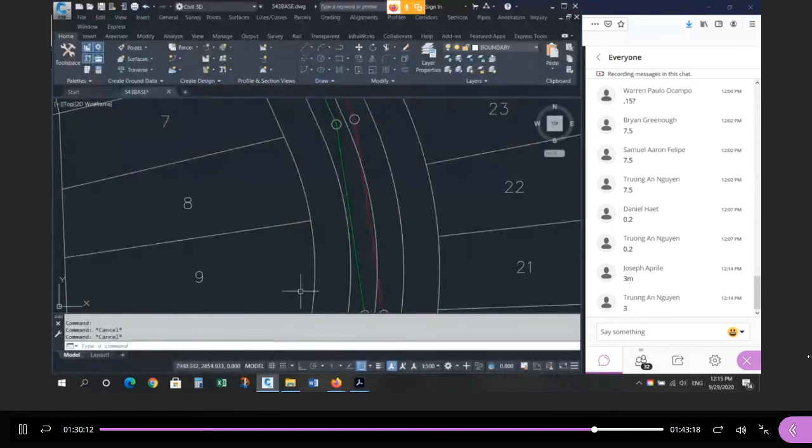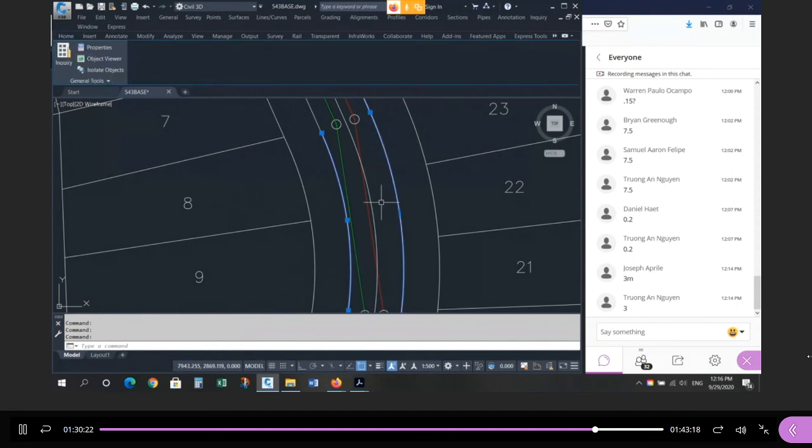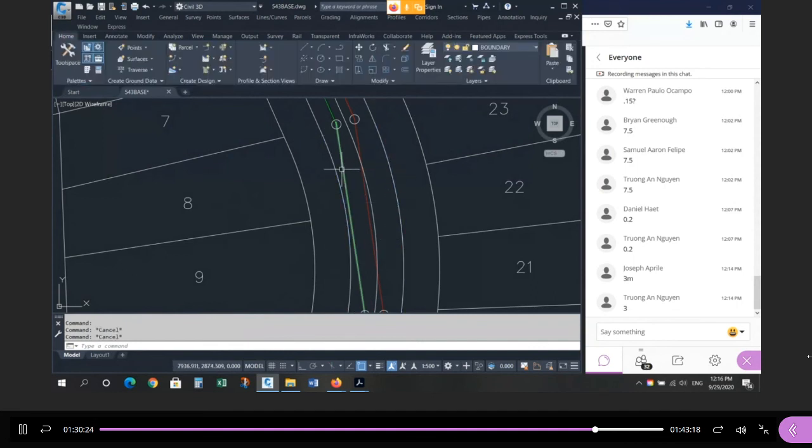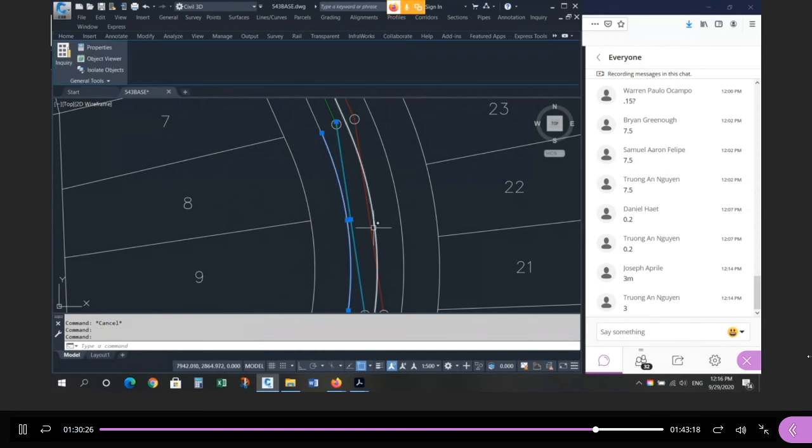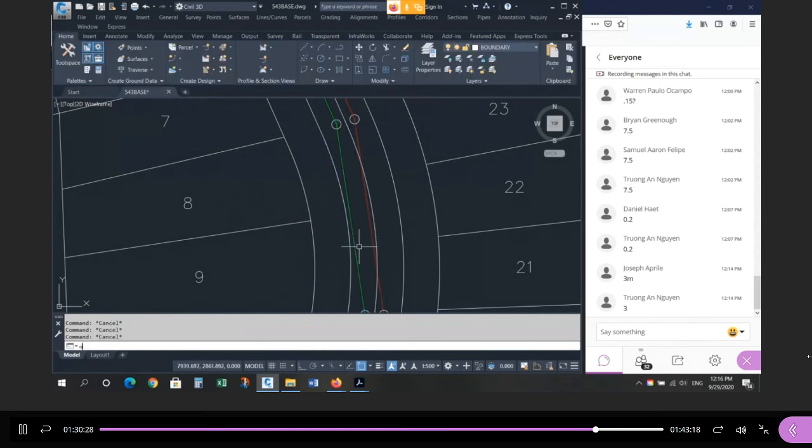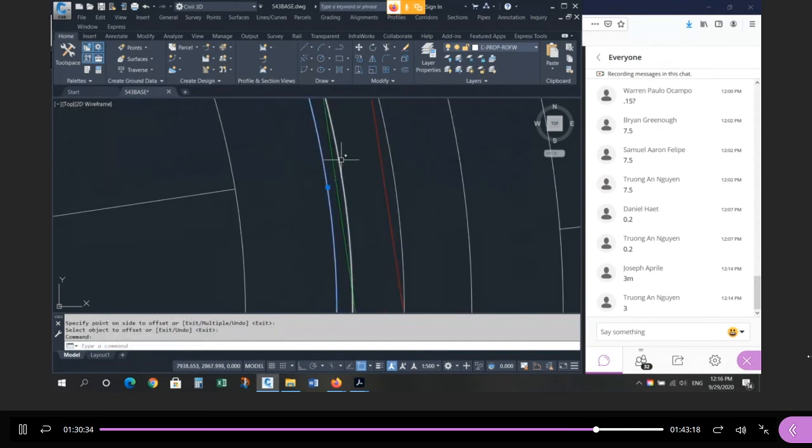So a bad solution would be this. If I move these further this way, now the sewer's in the boulevard, that's no good. So you stay between these two lines. There's two limiting factors. You go around a curve, the pipe starts to get close to the edge of it. You want to maintain your distance by at least 1 meter. Offset 1 meter. Make sure there's a no-touch zone. On the inside, stay 1 meter.